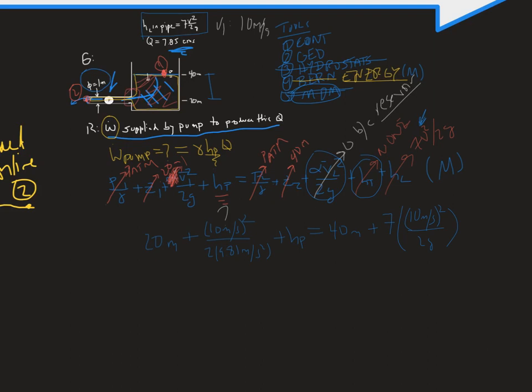Now you might say we didn't solve for the velocity in the pipe, we solved for the velocity when it left at 2. Well, this pipe is not changing diameter, so the velocity all along there is the same everywhere. So if we plug all these numbers in, I think all the numbers are in there. Yeah, all the numbers are in there. Well, I didn't plug g in.